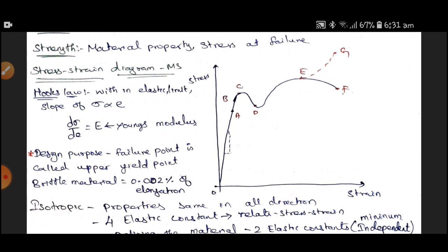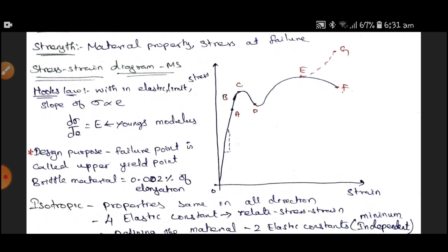How does it come about? In the stress strain relationship, stress is equal to load divided by area. After the ultimate stress point, the diameter or cross section of the bar keeps on reducing. If we take the instantaneous diameter, the graph is plotted at a higher position than point E. That is why it is called true stress and true strain.